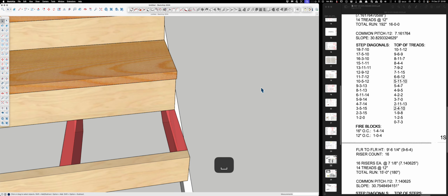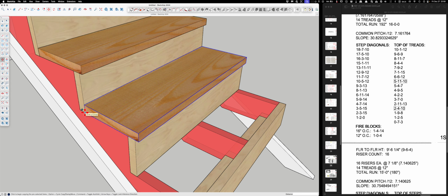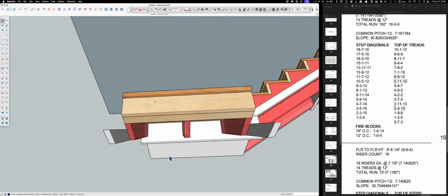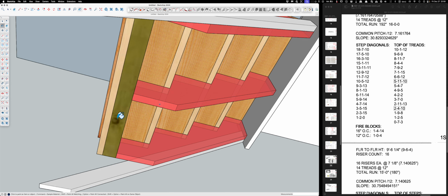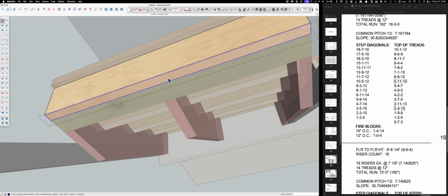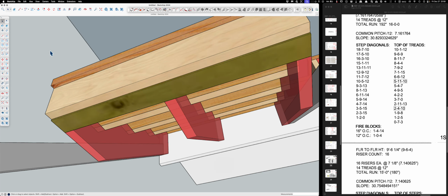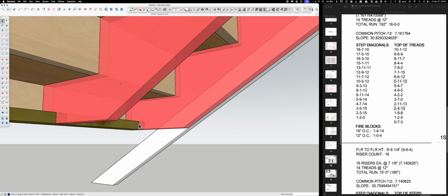All right, boom. And I'm going to put this tread on here. Copy. Okay. See how long these are? There's a couple things going on here. Where's the dark green one? We're going to pressure treat that because let's just say it's sitting on concrete. We're going to take this and go up 1/4 inch, 0.25, so it's not touching concrete.